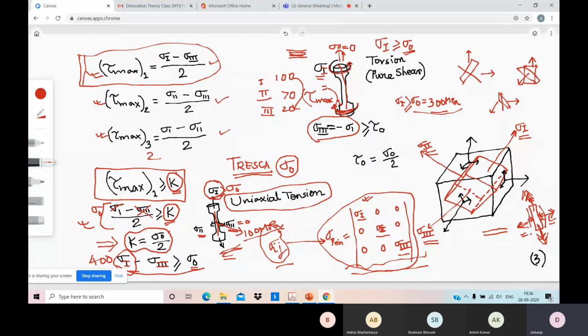So this is the basic theme of this problem. And one more very important value, suppose I consider uniaxial yield strength is 300 MPa. I am applying on a body three principal stresses in three principal perpendicular directions in a simple tension specimen. Suppose a tension specimen, three perpendicular directions, I am applying stresses 1000, 1000, 1000. Will the yielding occur?